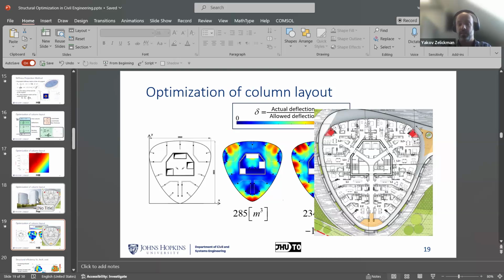Having said this, it's a super interesting question to see the trade-off, because on the one hand, to maximize the moment of inertia of the columns, you want them to be as far apart as possible. Yeah, exactly. But from the fully vertical or static consideration, it will be with a small inset inwards. So there's some interesting trade-off there. Exactly. That was my thinking.